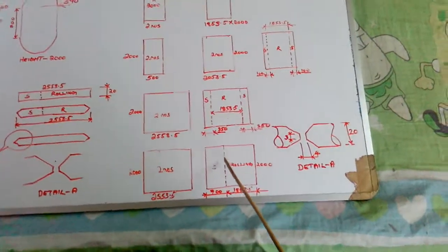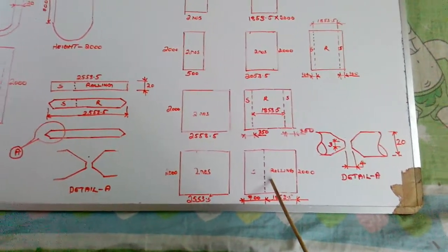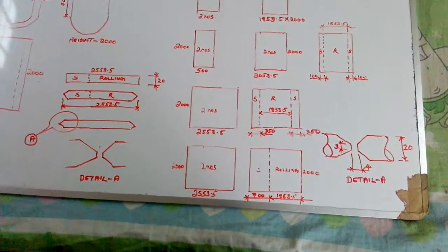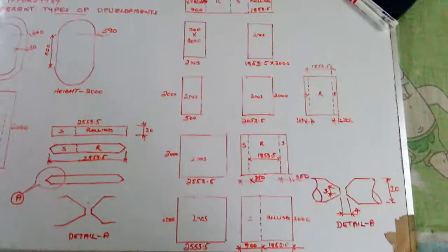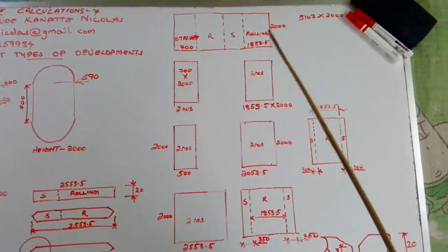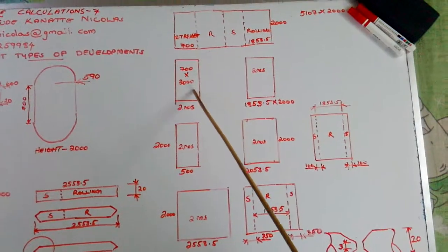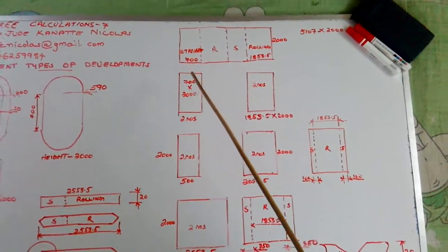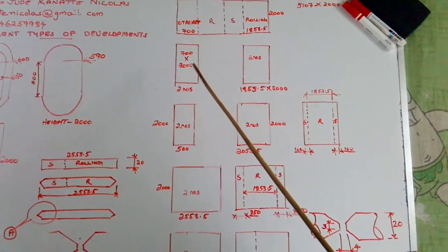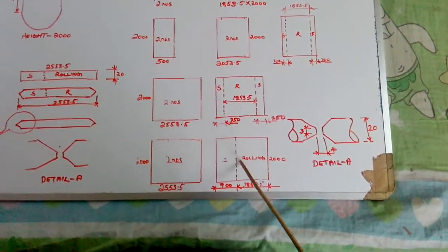Okay. So it has so many goodnesses and faults, but I can find many goodnesses. From two pieces we can make the same type of marking. We can avoid unnecessary weldings, because if we make it this way, we have to make two pieces of this kind and two pieces of that kind. Total 4 pieces. In each portion we have to mark, cut, bevel, set, tack, and weld. Afterwards, sometimes it may have distortion, shrinkage, or other problems. Those portions have to be chopped and ground. Finally we have to give it for welding. So many weldings are there, but here only 2 weldings are there. That is one goodness.